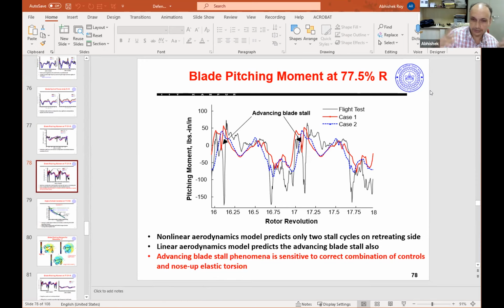This leading edge suppression vortex causes a delay in your stall by allowing you to extract more lift, but it comes at a cost: you end up getting a very high spiky pitching moment, which tries to pitch down the nose, the leading edge of the blade. This excites different kinds of dynamic motion in the blade, which further combine and cause more stalls on this side. So it's a slightly complicated answer, but that is all I can give you as a summary and overview without having to teach the whole thing from the ground up.